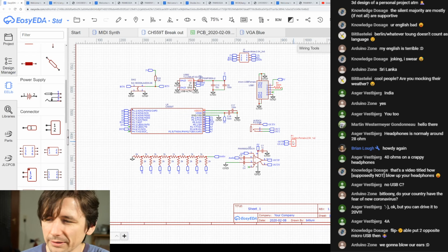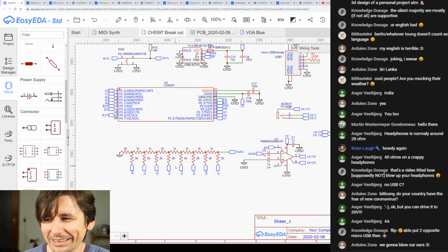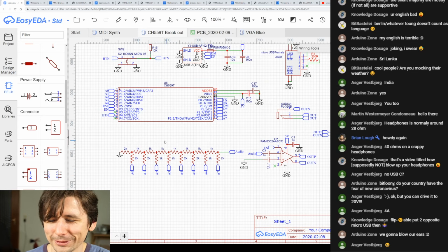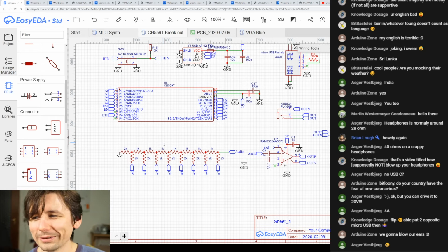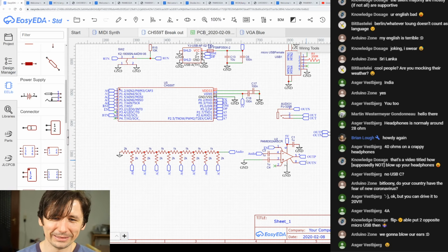Okay, so we added a connector here. This is the amplifier, this is the jack, this is only for power, and this is the DAC. So, 8-bit DAC. We will get a problem. There is not much quality to the audio if we have to use volume in software here. We end up having 1-bit or 2-bit output if the volume blasts out your ears with this amplifier.